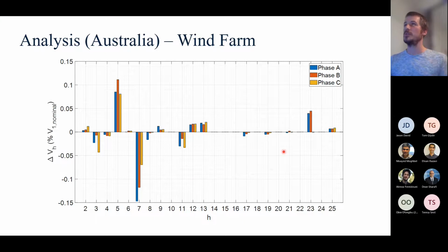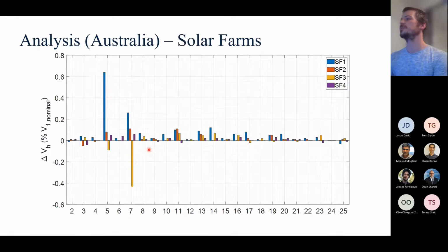And from memory, again, all of the information's in the report, but the connection point on the network was actually quite weak here as well. So you'd be safe to have assumed that the impact was going to be much larger, but actually we found that if you look at the THD, it actually goes down because of your 7th order there. Very interesting.